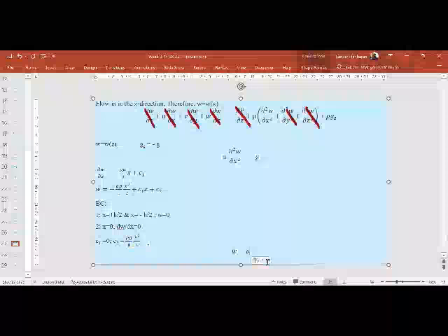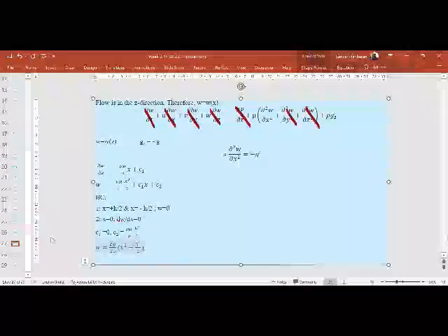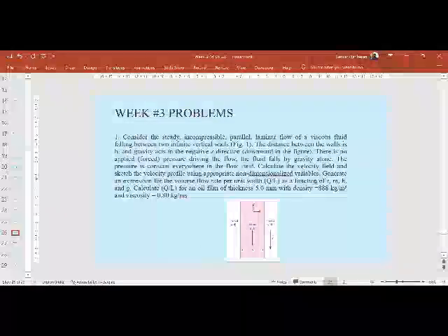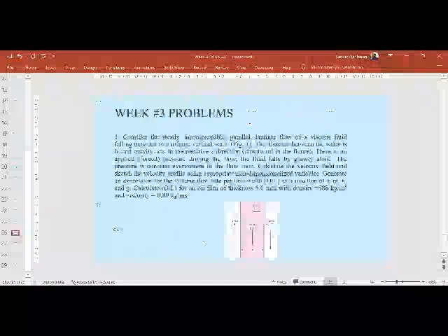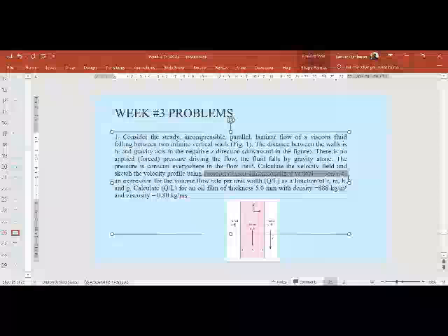So therefore W should be equal to rho times G by 2 times mu, times x square minus h square by 4. You'll get this as the velocity profile over here. And we see that it is a parabolic profile with respect to x. We just need to non-dimensionalize it now.